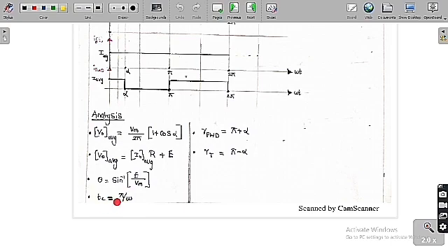The circuit turn-off time is the time for which the reverse voltage appears across the main thyristor. Simply we can say that the freewheeling diode was conducting in this region from 0 to alpha. When the freewheeling diode is conducting, we experience a positive voltage across the thyristor. From pi to 2 pi only, the thyristor was experiencing a negative voltage because here the source voltage was negative.